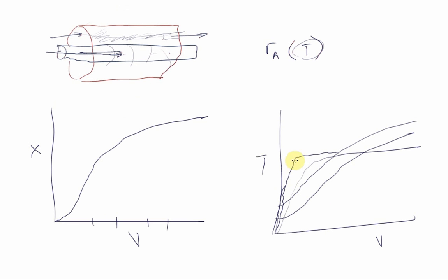And you see, in that case, we would get totally the wrong estimate for the volume. So we might get a factor, an order of magnitude difference in the volume that we predict. So if we say we are going to settle for a particular conversion, we might get very different volume predictions, and that can totally change our design costs. And so the accounting for the temperature has to be done carefully, or it might invalidate our design.